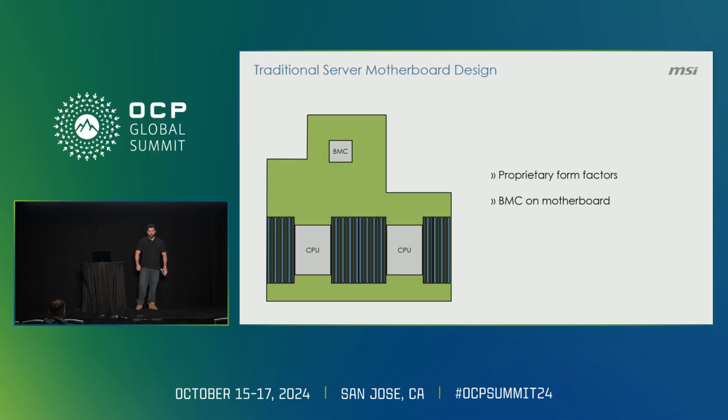The other issue is that the BMC was on the motherboard. This is fine if you have one server, one motherboard. But if you have multiple vendors, multiple different shapes and form factors, and multiple CPU vendors, it gets harder. If you're doing OpenBMC firmware development, you'll notice the BMC chip has a lot of multifunction pins, so the actual hardware implementation is different from board to board. Your hardware engineers and firmware engineers developing OpenBMC firmware have to stay on top of the hardware specifics of each board, and the workload explodes exponentially with the number of platforms you have to support.